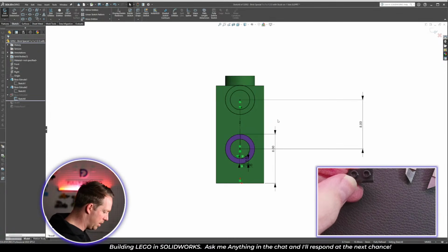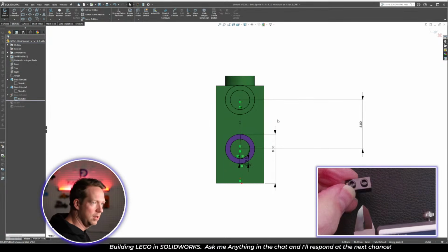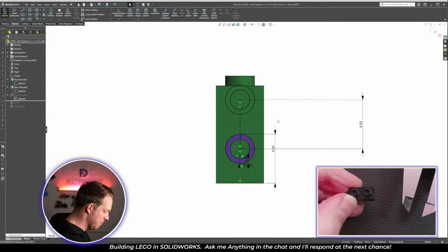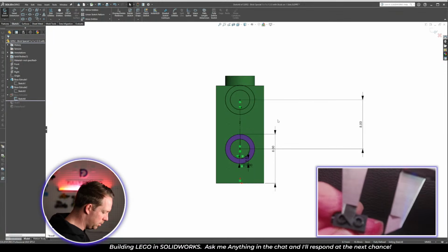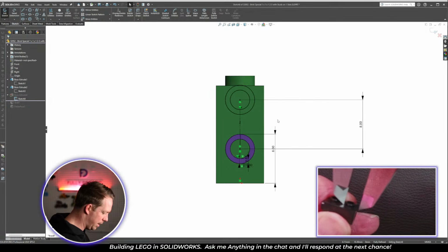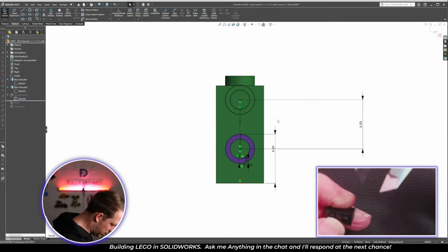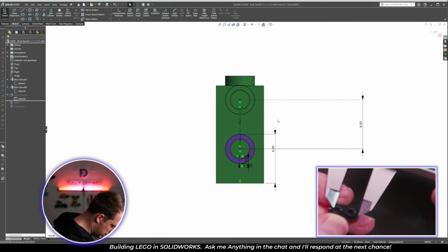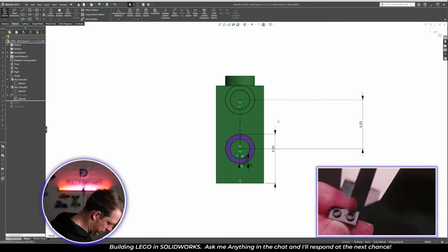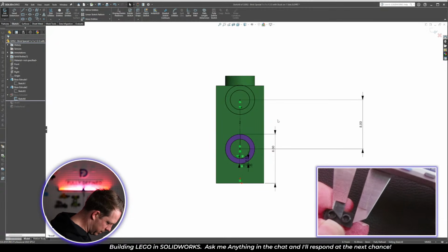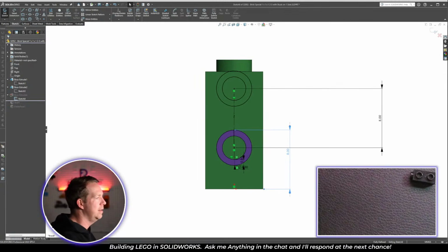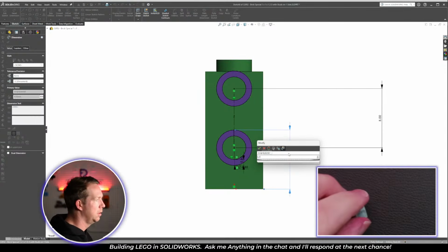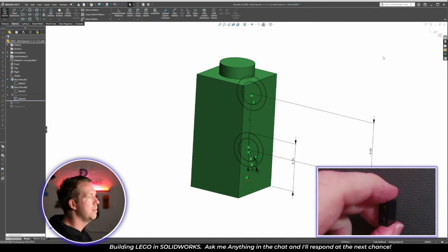So how can we try and work out the right position from here, like to get a dimension from edge to edge? There's a few ways. One might be, you can do it by eye from the middle, or the calipers won't go down all the way here and get that edge exactly. They'll get very close. And I'm on a little bit of a lean, but I'm getting 6.7. So that 8mm, let's change that to 6.7. And that updates the position of both of them.